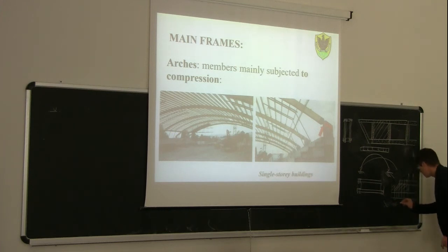300,000 kilogram per square centimeter will be 3 million newton per square centimeter. And then for newton per square millimeter, we need to take away 2 zeros, so it will be 30,000. No, I think it's right. You said 30 gigapascal, and I think it's right, because 300,000 kilogram per square centimeter would be 3 million newton per square centimeter. To get newton per square millimeter, we divide by 100. So this would be 30,000 newton per square millimeter, which is megapascal. So for gigapascal, we divide by 1000, so it was right.